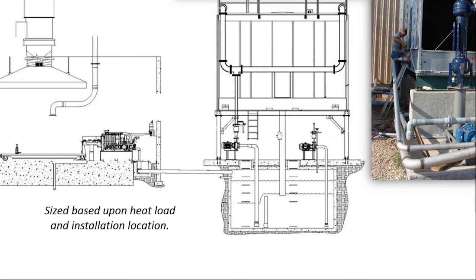There we go. So what's happening in the system is here is this underground reservoir, in essence, and I've got a pump system that is lifting water up into the top of the cooling tower. The water is being gravity drained back down through this large pipe into the cold side. While the water is gravity drained over some media, a fan is blowing air across it, and it's the fan that is carrying off heat via evaporation.